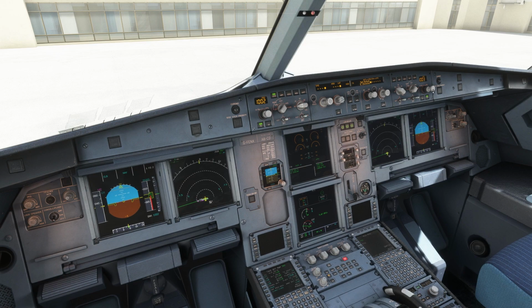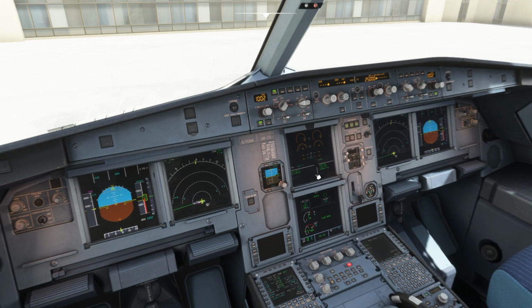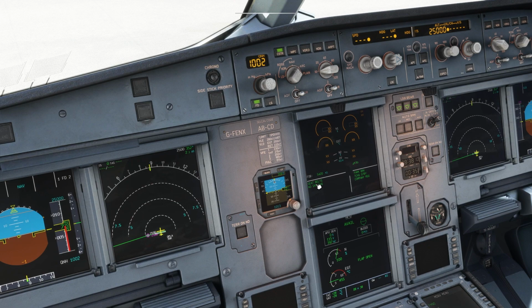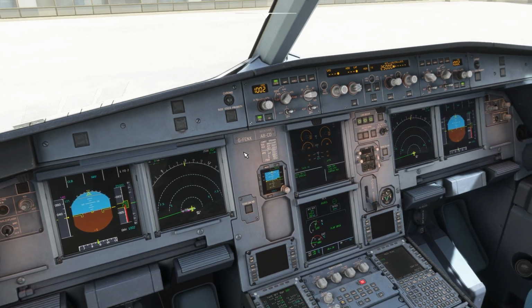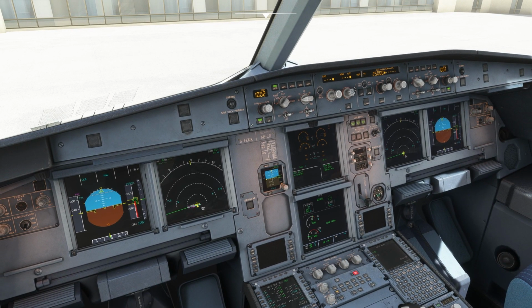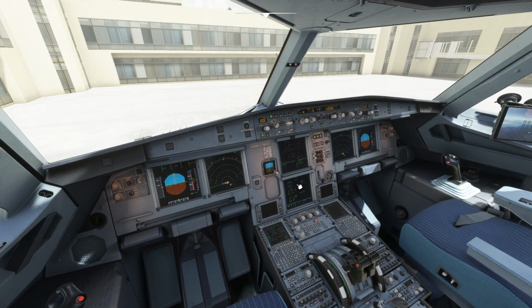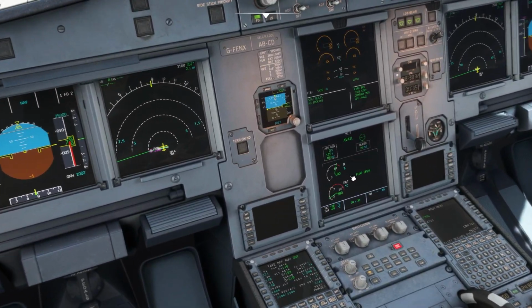See, this is what I was telling you in the beginning, that the flight warning system is really nice. If you hear a chime, you can just refer to the flight warning system and you can see what the error is, and then you can fix it. So now the QNH is adjusted, speed is in the manage mode, altitude is in the manage mode. I will tell you during the flight how the manage mode works, because there are two modes selected in manage, but I will explain it to you during the flight.